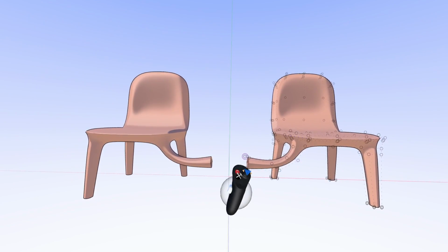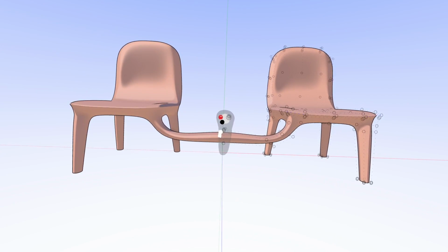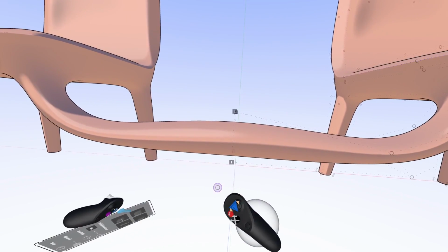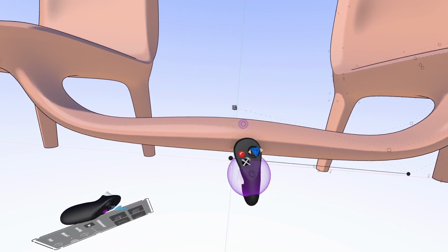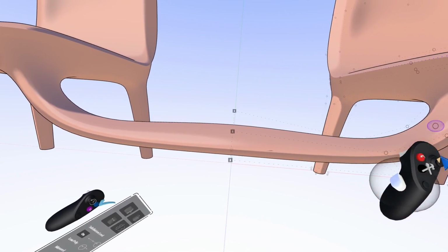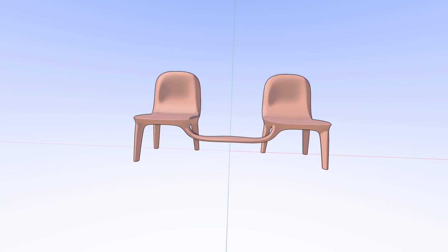And of course we can take those edit points now and connect them across the mirror plane. And so now when we zoom in, you'll see that those edit points connected to the mirror plane are represented with a black keyhole frame. The nice thing about connecting sub-D objects across the mirror plane is the continuous smooth curve. You'll notice that you don't get this without a lot of manual effort when using NURB surfaces.